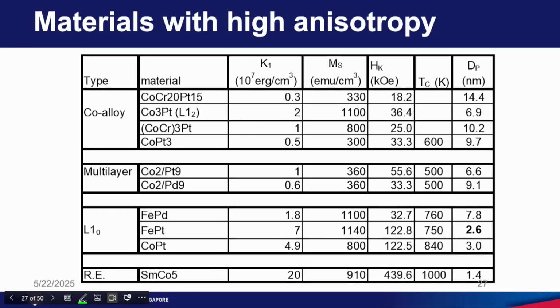The second advantage is the thermal stability. So for in-plane MRAM, we said the minimum diameter is around 60 nanometer. Right? We cannot shrink the MRAM to be smaller than 60 nanometer. But materials with a perpendicular anisotropy have very large anisotropy values.